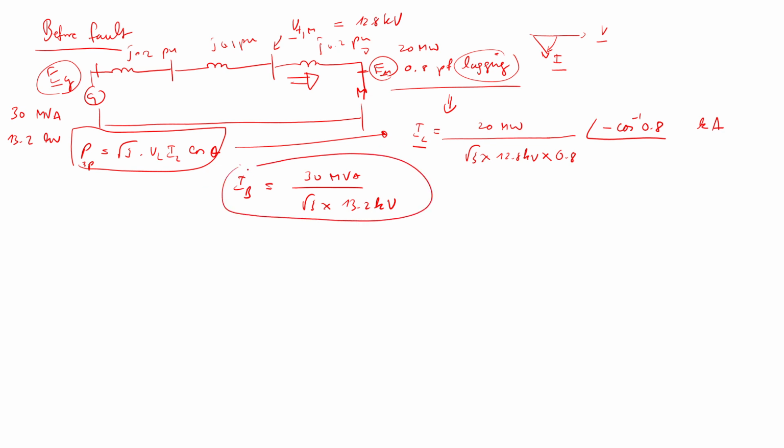Remember, the IB here is in real quantity. There is no base in complex quantity, right? Remember this fact, right? So you can change this IL in real quantity to be per unit, right? You take this divided by this, right? I'll just draw a rough calculation, and I have computed everything in the slides, and you can recheck this yourself, right?